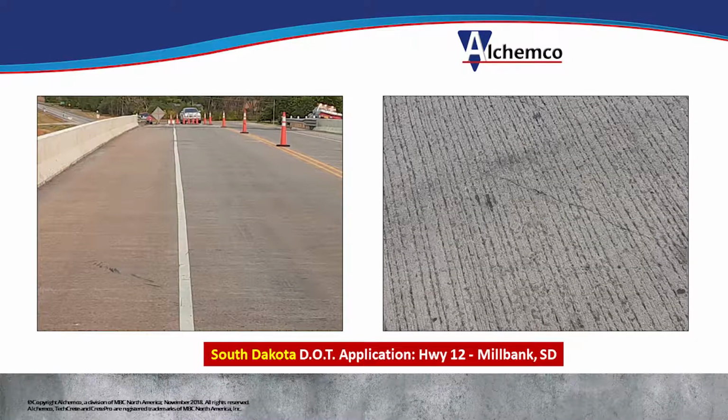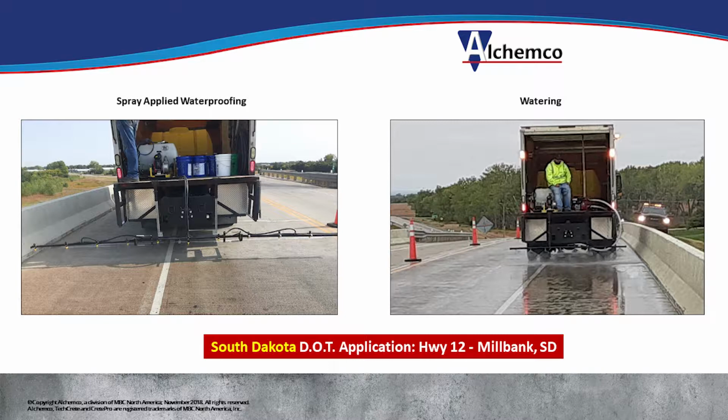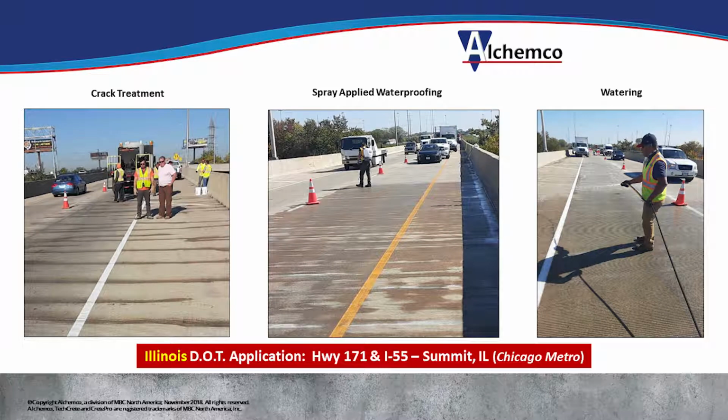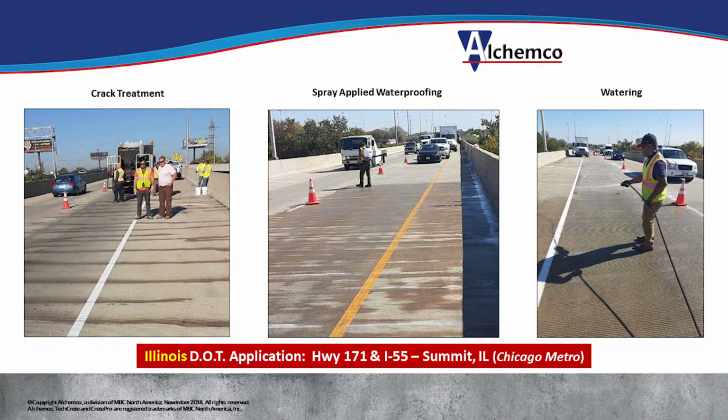Here, just to wrap up this presentation, are a few of the projects we were talking about: South Dakota, Illinois. One thing you're able to see, mainly on this first picture, is that the very first step when we are spraying this material is to flood all the cracks with the product. That's a critical step because we want to make sure that there are enough chemicals available to seal that crack. So the very first step is someone with a backpack sprayer flooding all the visible cracks.